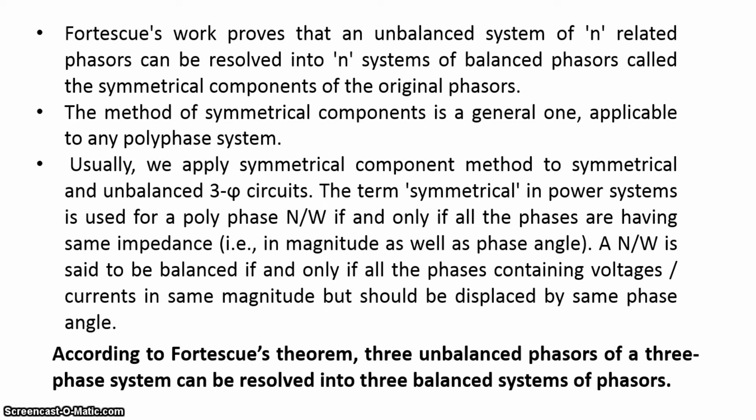The term symmetrical in power systems is used for a polyphase network if and only if all the phases have the same impedance, that is, in magnitude as well as phase angle. A network is said to be balanced if and only if all the phases contain voltages or currents of the same magnitude but displaced by the same phase angle.